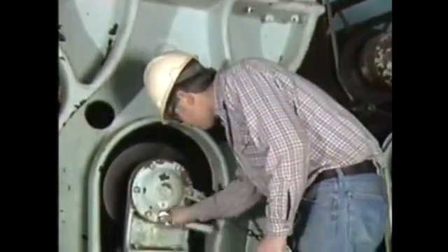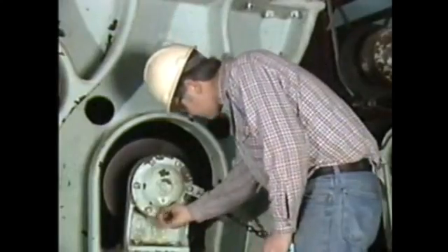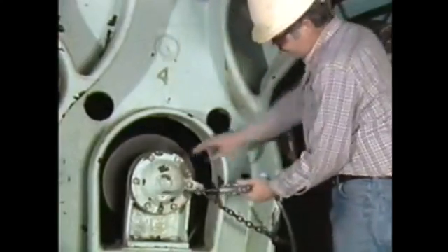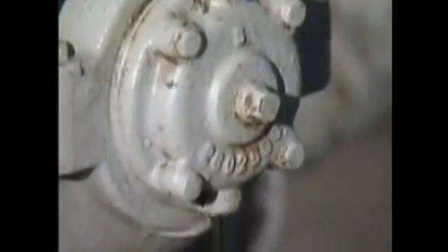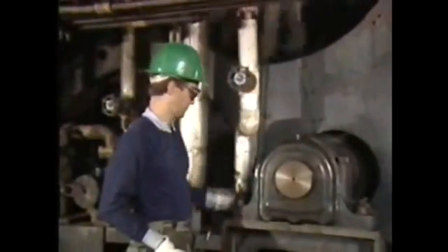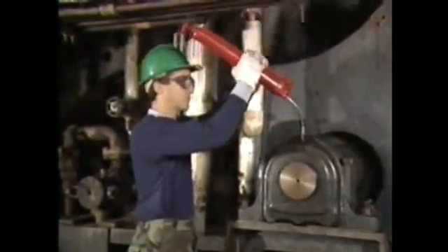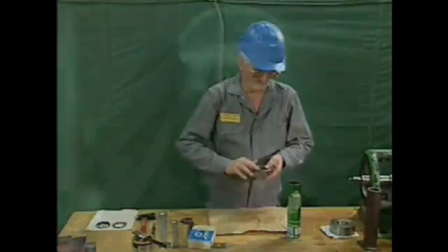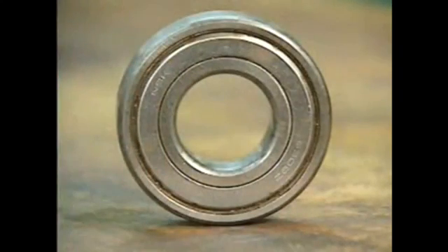Another way to lubricate bearings is with grease. Grease is generally used to lubricate bearings that are installed in machines that operate at slow speeds under heavy load, such as large circulating pumps. When adding grease to a bearing, it's important to use a grease that is compatible with the grease that is already in the bearing. Mechanics generally use one of three basic methods for greasing a bearing. They can grease the bearing with a grease gun, pack the bearing by hand, or use a grease cup. These methods are used only with bearings that are not sealed. Sealed bearings are permanently lubricated and they do not have to be greased.